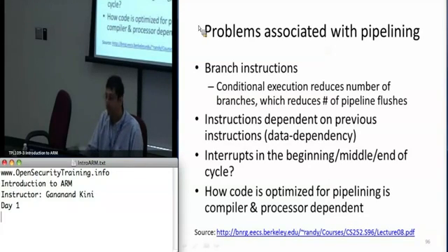So we have to be careful when we're pipelining, and that's the reason I brought up interrupts. Interrupts are a good example: you have changed the values in the register, an interrupt occurs, some other piece of code starts running, but what happens to the values in R2? I'll go into a little more detail on interrupts later, but that's a very good question. If you're writing an application level program, interrupts are somebody else's problem. You want to make sure that, when you're in certain sequences, you're not messing things up.